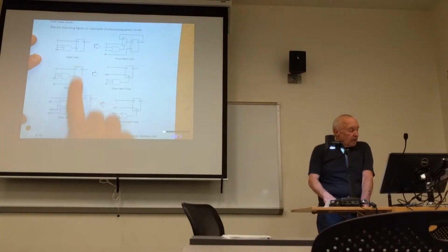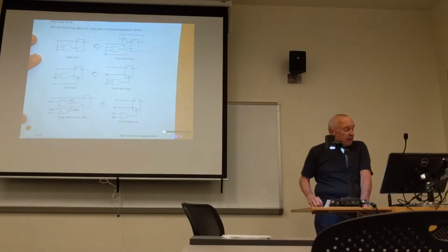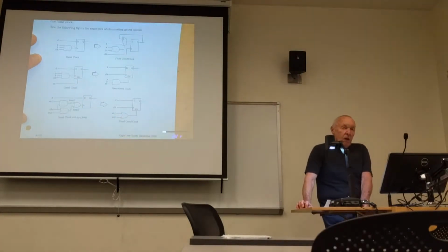Here are a couple different gated clock circuits, and again, the issue here is your clock is running continuously. It's a free-running oscillator. So if you don't gate that clock signal, registers will respond and update their output on every clock pulse, and that may not be what you want.